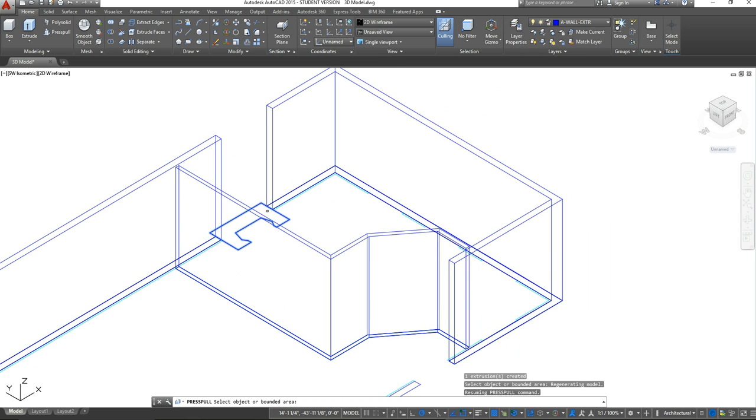And now I want to actually deal with this fireplace. So I'm going to do the standard height of a fireplace at 54 inches. And then we're going to deal with actually closing up that gap. So I'm just going to, again, hover so that that full area is selected. I'm going to click once to start to pull it up. And I'm going to type in 54 inches and press enter. And that's going to, again, extrude that portion up for me.